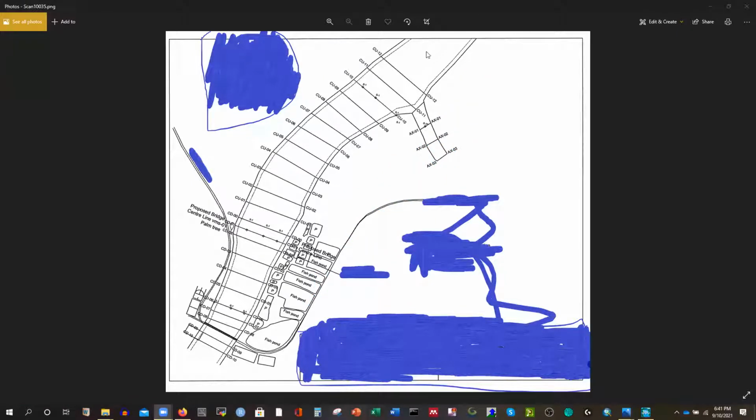So that's the plan. That's the upstream, what is coming from upstream to downstream side. At the same time, you have to keep in mind that is the left bank, and that is the right bank. For the HEC-RAS model, it matters: water flows from upstream to downstream, and if you are standing there looking at the flow, the left side will be the left bank, and the right side will be the right bank.